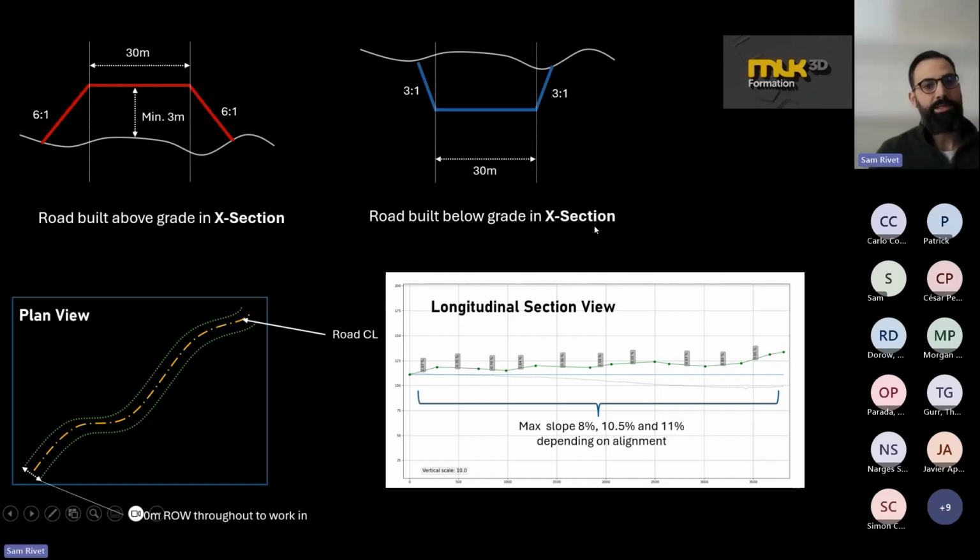As well, this is going to be a balanced cut fill project, right? So the amount of volume that we excavate to build a road, we want it to equal within 1% the amount that we need to fill. And this is important in a real life application.